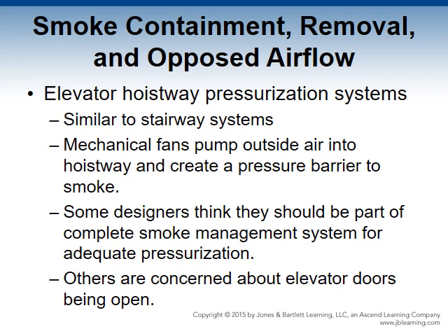Other design professionals believe hoistway pressurization is unnecessary and are concerned about the requirements for elevator doors to remain open when recalled to their designated floor level. If doors stay open, a major opening in the pressurized hoistway occurs. The concern can be addressed by having doors open and shut at intervals. Firefighters can also use elevator keys to take control of the elevator cabs.